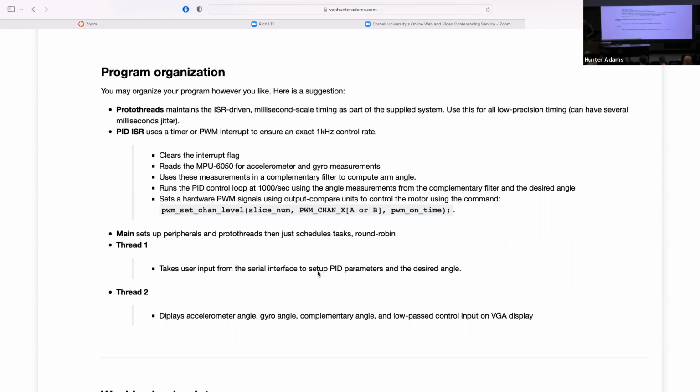Why didn't I set up the demo code that way? Well, remember that from lab 1, way back when we were talking about timers and timer interrupts, one of the things that we spent quite a bit of time talking about was the levels of abstraction associated in particular with those timer callback functions. So you may recall that at the lowest level on that timer peripheral, there are those 4 alarm registers, and you can write a value to those alarm registers, and then when the value in that register matches the lower 32 bits of that incrementing microsecond timer, an associated low-level interrupt flag is thrown to which we can tie an interrupt service routine.